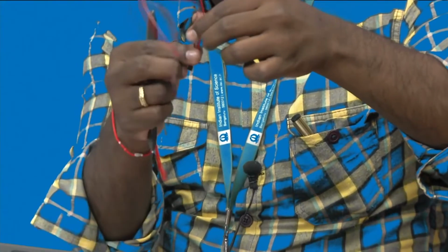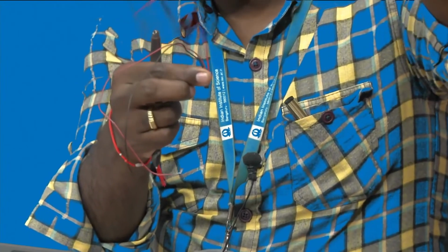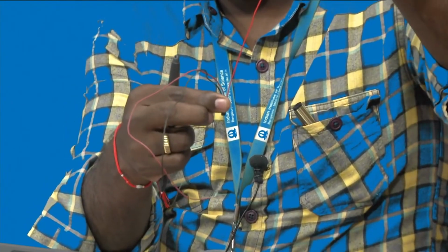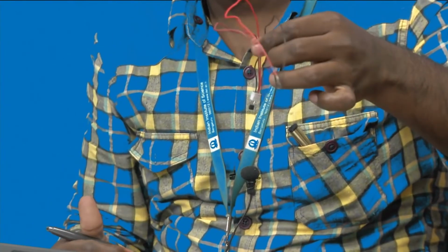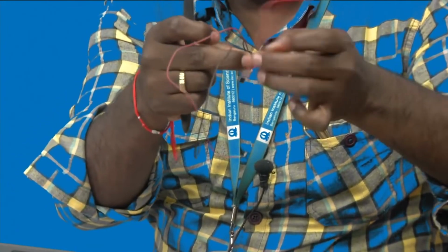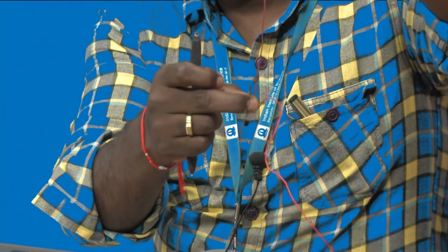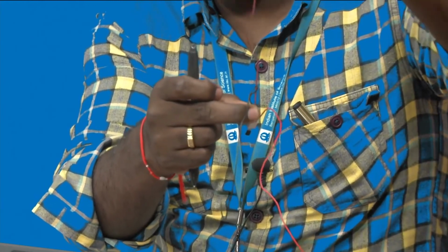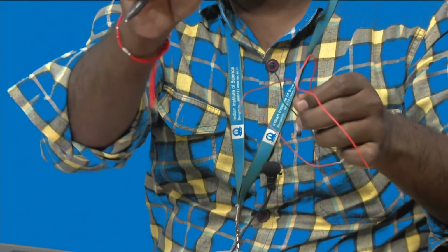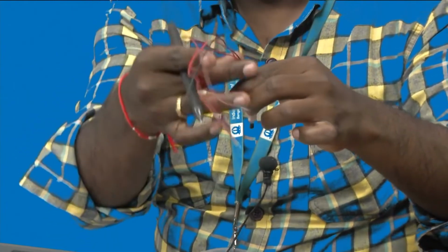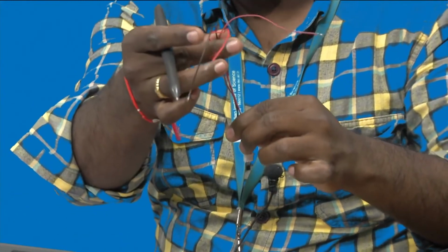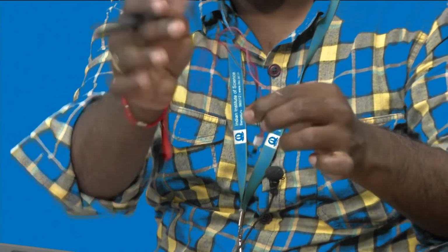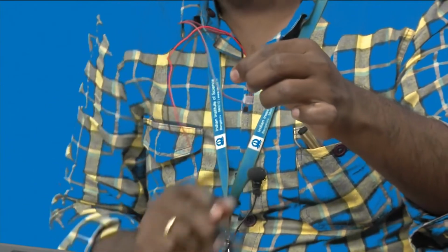So here we can see that this red wire of our RMC cable connects to positive, so positive voltage which can be applied from 4 to 20 volts. Then the center, which is a brown cable, is Vout. Whatever voltage we measure is with respect to the ground, and the ground terminal is a black wire. So we have connected in such a way that connecting these wires to a power source and an oscilloscope or a data acquisition device will directly connect to the LM35 temperature sensor, right. This is what we have seen from the data sheet.